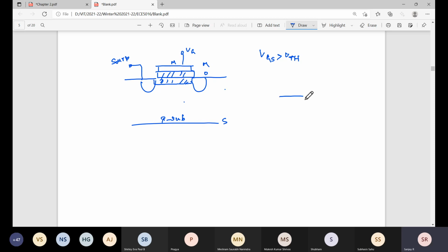So you always remember in a PN junction, I am not giving any supply voltage. Is there any depletion region there? Yes, sir. Definitely a little bit, because there are more electrons on one side and more holes on the other. They will try to diffuse. That diffusion will form the depletion region. That's the intrinsic built-in potential. Without giving the supply voltage, there is some built-in potential, 0.7 volt. Like that, you can assume intrinsically some channel exists, which is not sufficient to turn on the transistor.